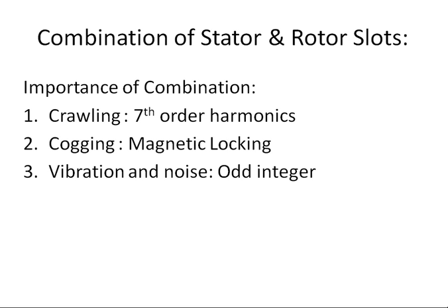This rotor winding or rotor bars will have current flowing through them. The direction of this current is given by Lenz's law. These currents will also produce flux, and there will be an interaction between the stator flux and the rotor flux, which will lead to the production of torque, because the basic principle of the motor is that a current carrying conductor placed in a magnetic field will experience a force. So the torque produced by the motor depends on the current flowing in the stator and the current flowing in the rotor, and their fluxes which interact with each other.